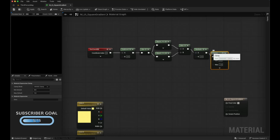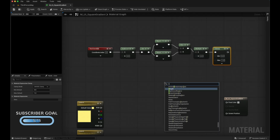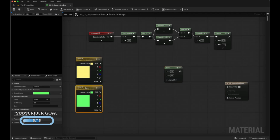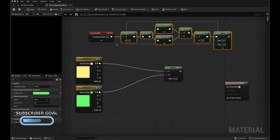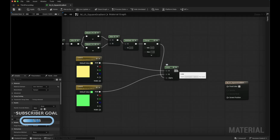Now we have to clamp it between 0 and 1. By default, it will be minimum 0 and maximum 1. So this is going to be our alpha value in our lerp node. Let's create a lerp node. So A is going to be our color A and B is going to be our color B. Alpha is going to be our clamped value. So let's pull all of these nodes behind lerp. The output of the lerp value is going to be our final color. So once we connect it to the final color, we should get a square gradient.